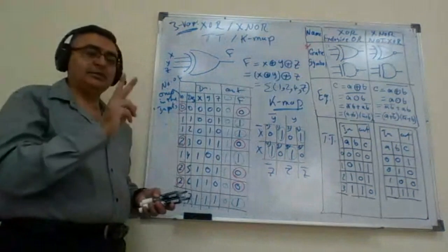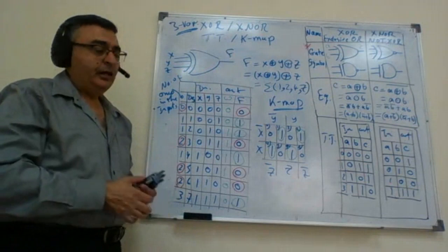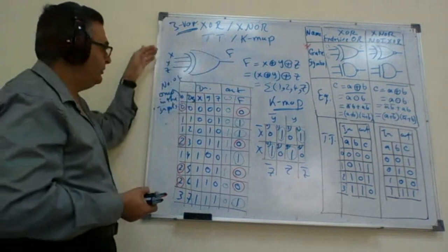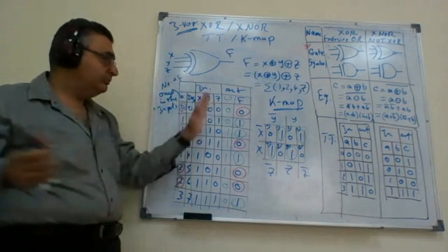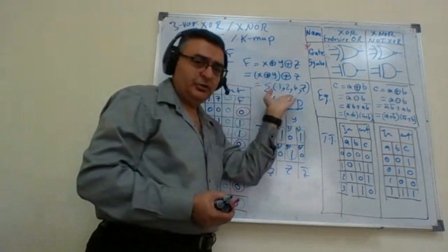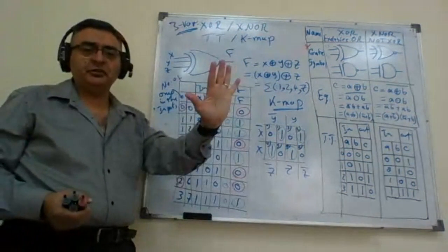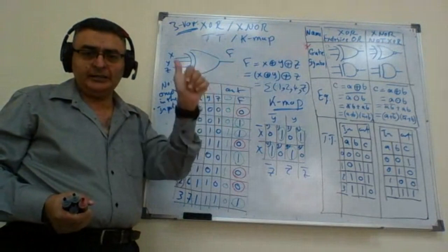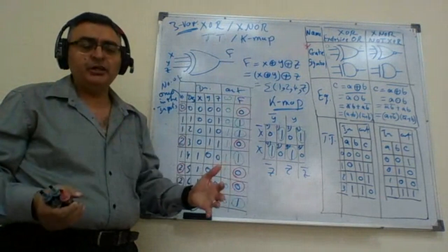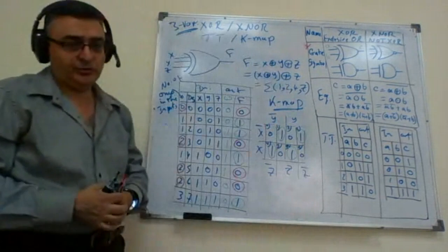So there are 2 formats for the XOR, and similarly for the XNOR. Either you represent it as it is, 1 gate, 1 tau delay with the 3 inputs, and you definitely win. Or you go to the sum of minterms representation, which means a huge circuit of 5 different gates, 4 AND gates and 1 OR gate, each of them with 3 inputs, in order to implement the XOR.